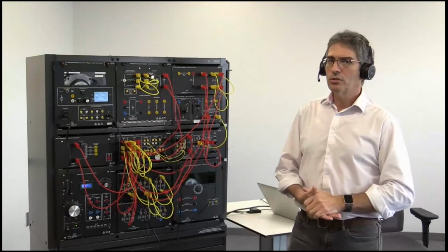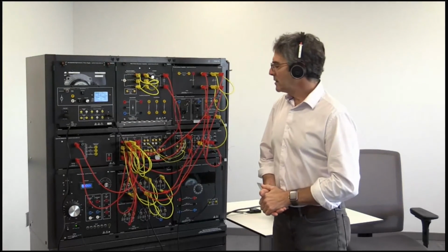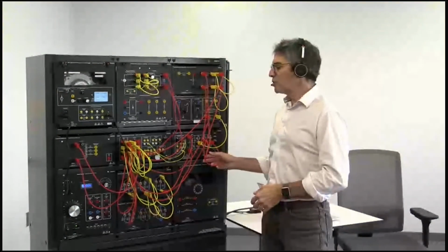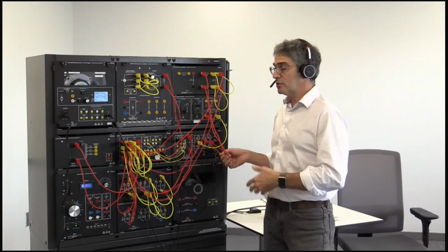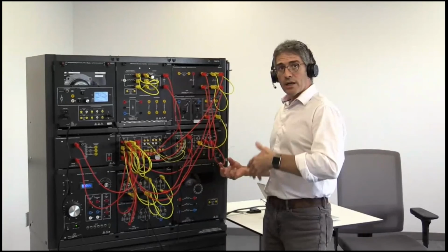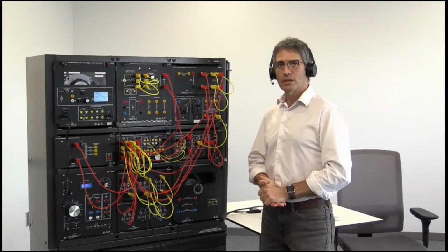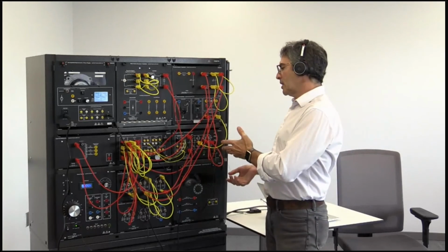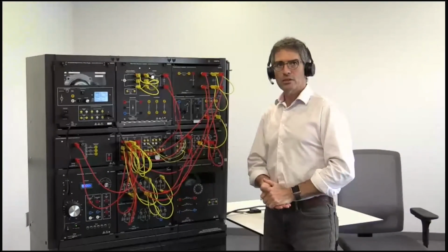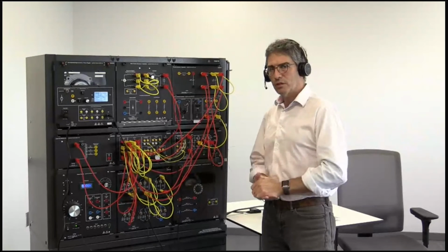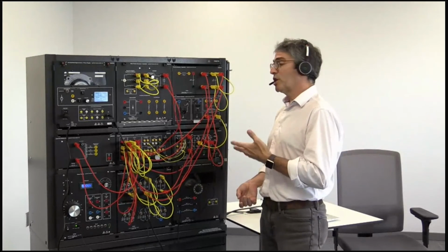And then there's another protection circuit that makes sure that we do not draw too much power from the inverter, because of course an inverter has a certain power capacity because of the power rating of the transistors and all. So in our case, we set it to 250 watts initially, but you can change that and play with it.